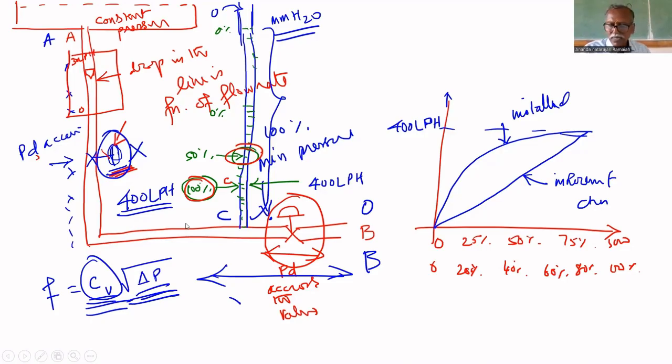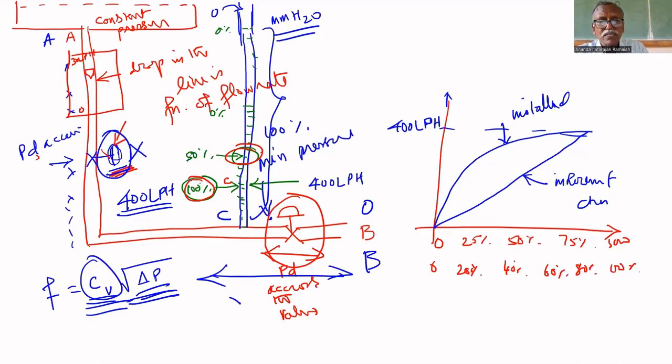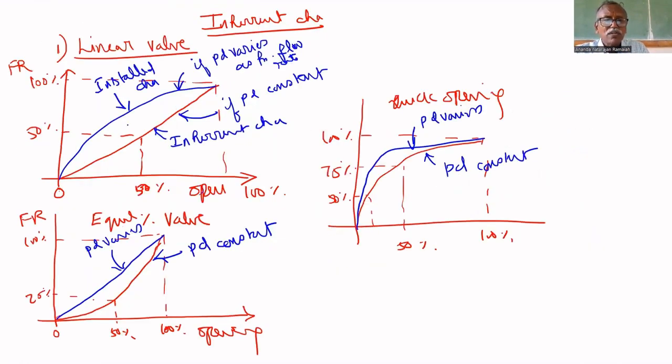The next experiment is... here, one point I want to mention is, we are saying that it is perfectly linear for inherent. Installed, it gives quick opening. Similarly, you can expect that you will get this.